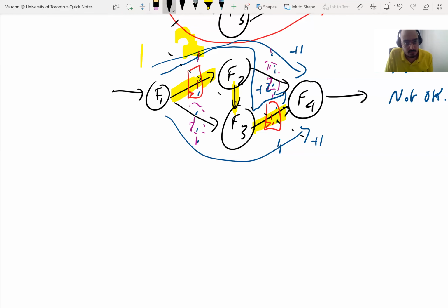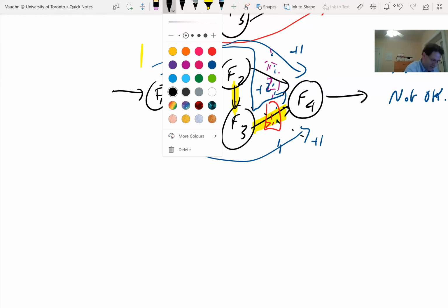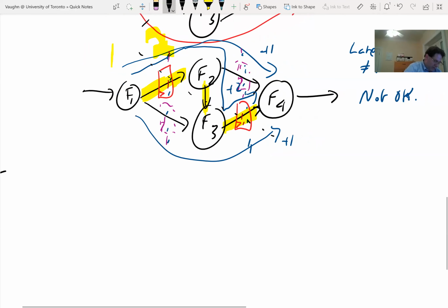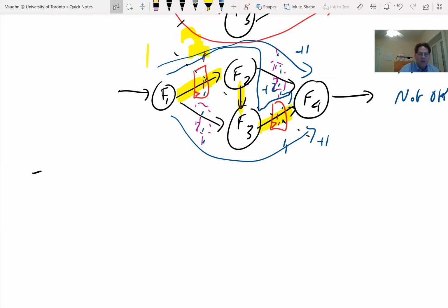But if you get confused, and it's easy to, the most fundamental one is you've got to balance all the latencies. The cut test only works in a subset of designs that are, as I said, feed forward, because there are some other rules that it doesn't capture. But feed forward designs are an important subclass, and you're going to use them in assignment 1 and 2. You're going to largely be able to do things with feed-forward efficient circuits.